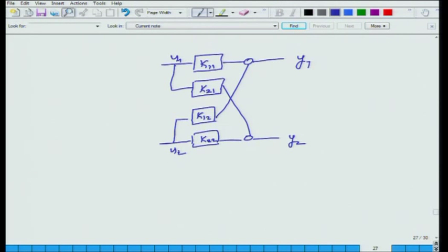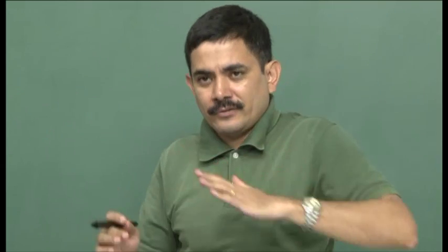But because I make a change in u2, the interaction term, the cross term causes y1 to deviate from set point. So, I keep adjusting u1 until y1 is brought to set point. Once I have done that, because u1 has changed, y2 would have deviated. So, I keep adjusting u2 to bring y2 back. I keep doing it again and again. Hopefully, if I have done it sufficient number of times, y1 and y2 will get close enough, if not exactly, to their set points. So, that is the basic thinking that I will apply to derive the Niederlinski index.